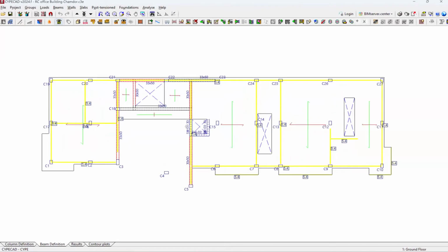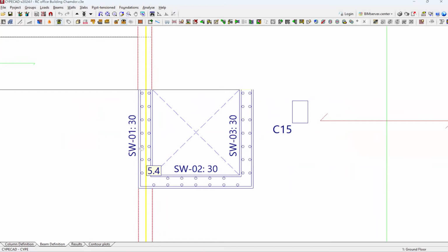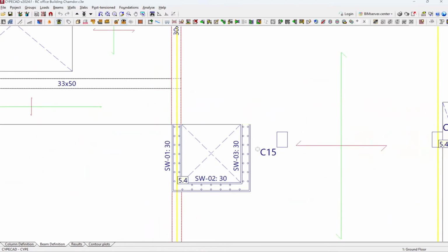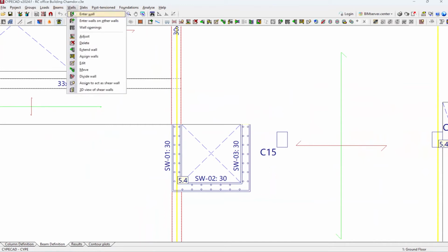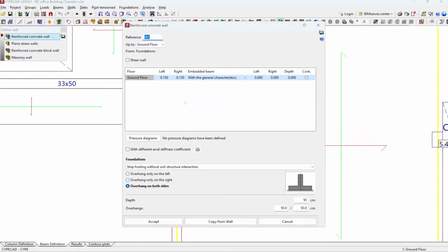Then after that, because the building is going to have a lift shaft, I took that opportunity, where the lift shaft is going to be, well positioned exactly in the center of the layout. So I had to divide by shear walls. How do you define the shear walls? You define shear walls by just entering walls. You go to reinforced concrete walls. Then you define your column position, your wall thickness. In this case, the shear wall is going to be 300 mil